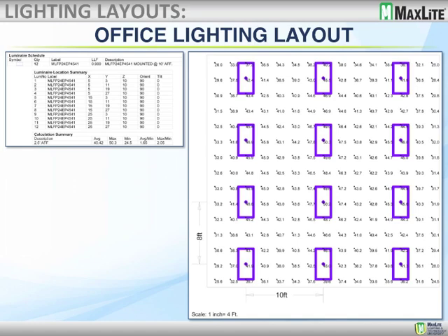So on average, an office back in the 80s, when everybody was designing these things, they were designing with 4 T12 lamps to get you almost 60 to 70 foot-candle average. Nowadays, that's way overlit, and we end up going about 40 to 45 foot-candles average for office lighting.